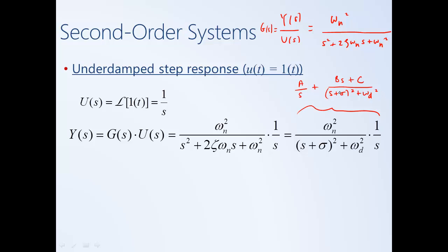but looking at this, we may recall that a system with this sort of denominator looks like basically a sinusoid that's been shifted in the s domain. So if we had s squared plus omega n squared, or s squared plus omega squared, that's either a sine or a cosine. And then if we shift it by an amount sigma, then that adds an exponential decay to it. In the case of a sine, we're going to want a numerator that's exactly equal to this, omega d. And in the case of a shifted cosine, we're going to want an s plus sigma in the numerator.